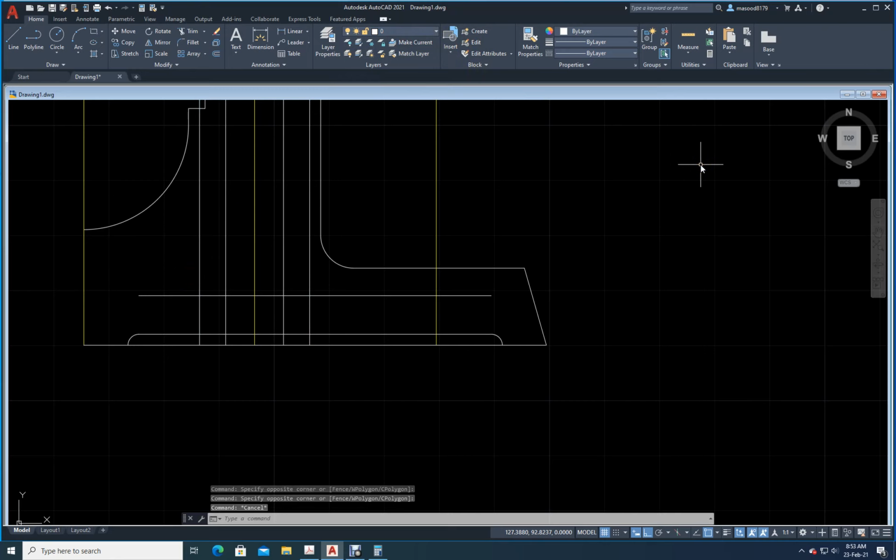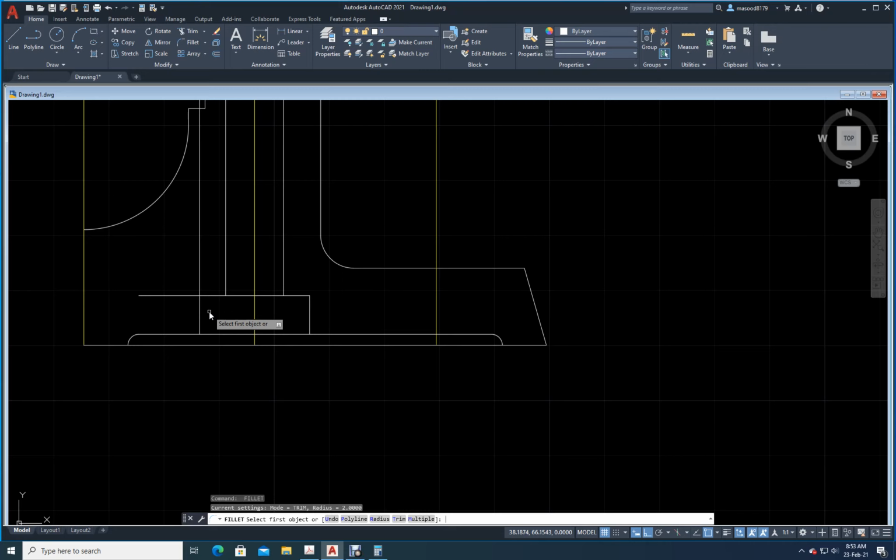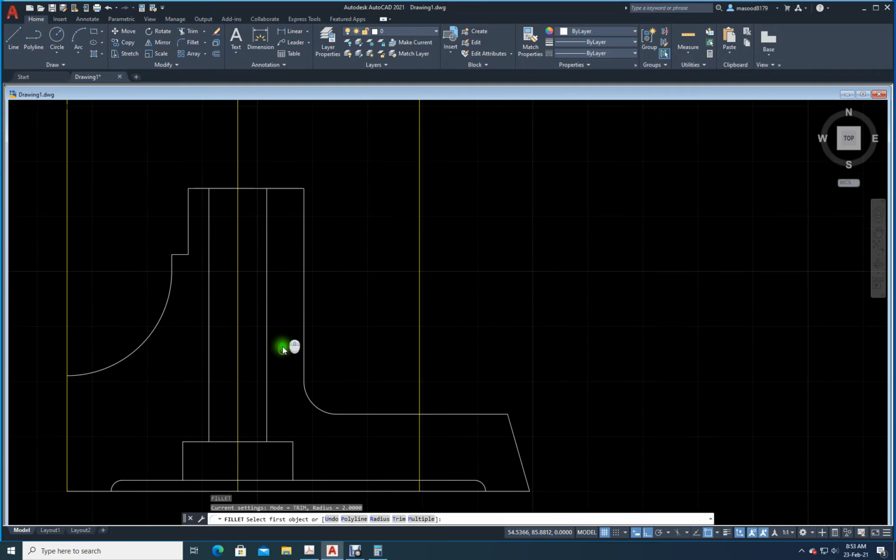Now I need to remove, I need to trim. Trim what? You don't need this, is it not? You don't need this. Of course, be careful in CAD 2018, you need to select the boundaries. I don't need this. Okay, enter. Now for this portion, I will press shift, go to fillet, then select this line and this line, automatically it will do. Again remove, space bar, again press shift, this one and this one, see that? Now enter. So this part is also done for you.